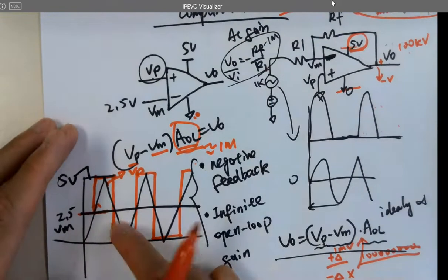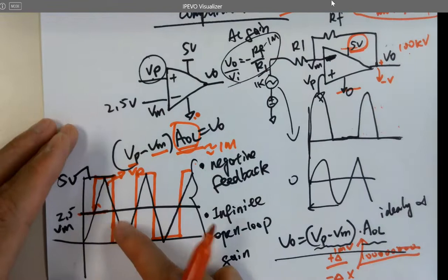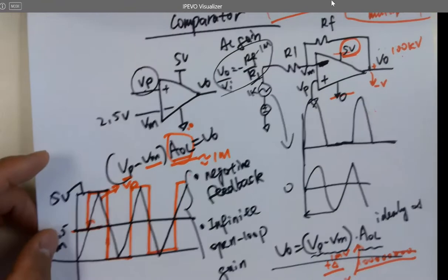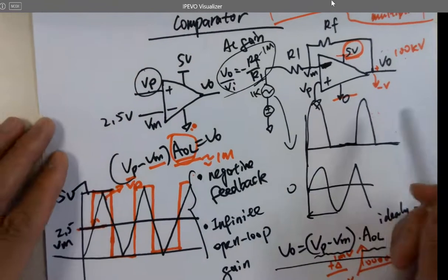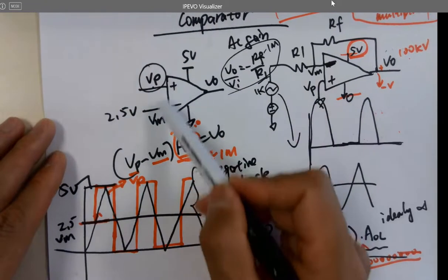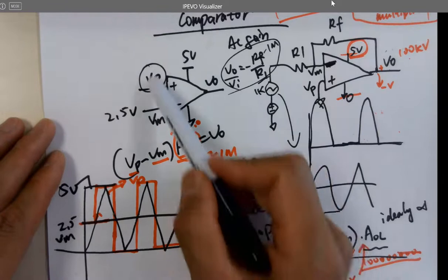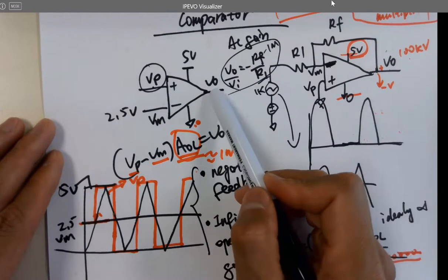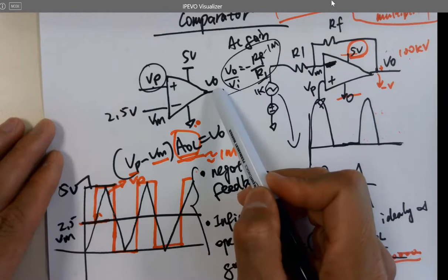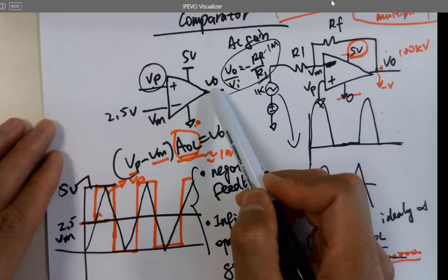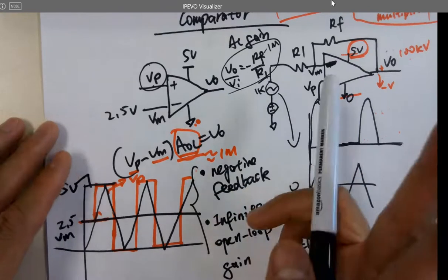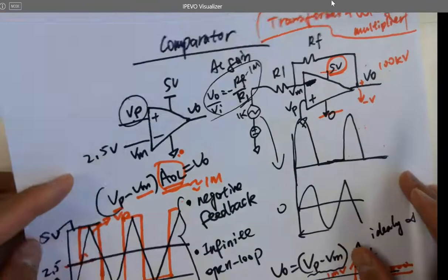So the comparator is going to do this. Why is it called comparator? It compares these two nodes, which is larger, and flips this voltage to indicate which one is larger. Whenever this is 1, which is larger? If VL is 0, VM is larger. So it's comparing these two nodes. That's why it's called a comparator.